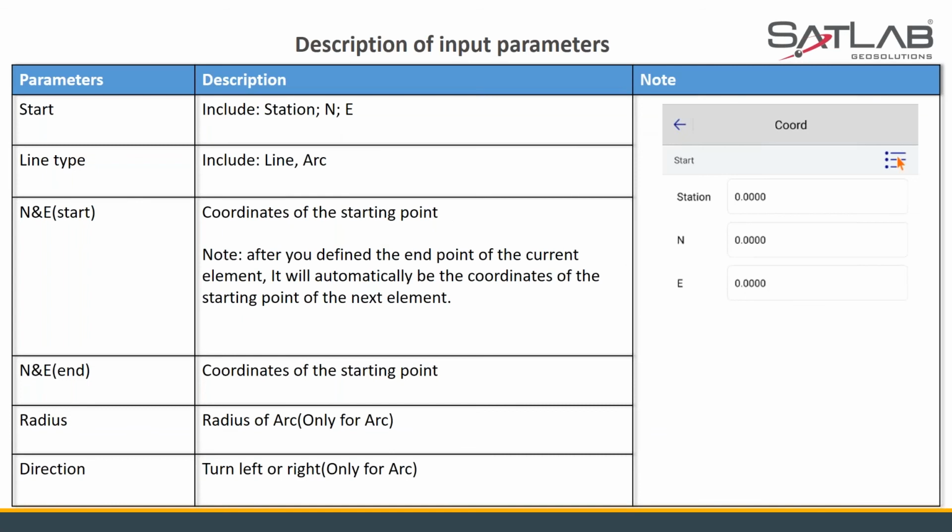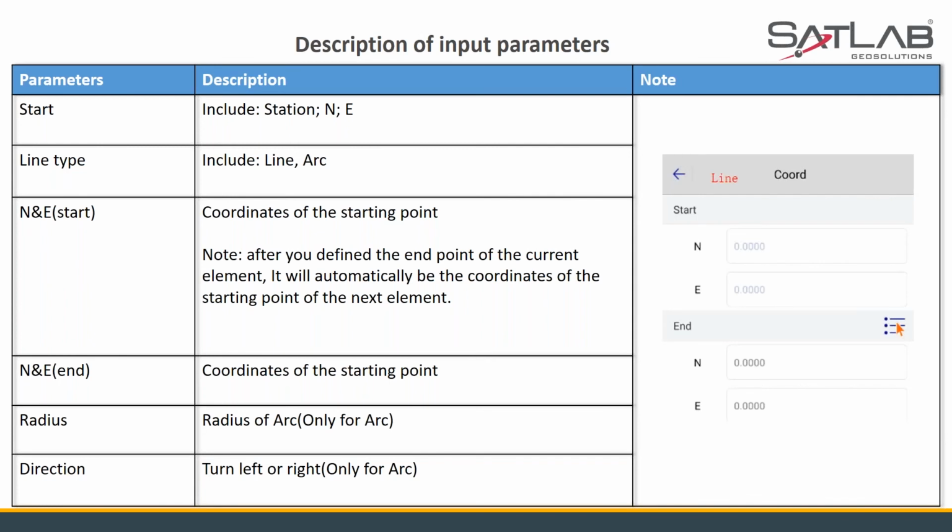After then comes the coordinate method. The coordinate method is similar to the element method, but here we are just using the coordinates. That's it. We are using the northing and easting. We're not using the spiral in, the spiral out. It's specifically this particular method. It's being rarely used because there are no smooth curves and all. I'll show you over here.